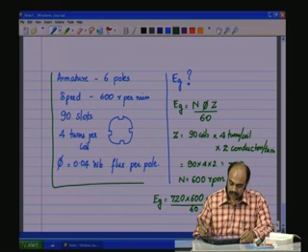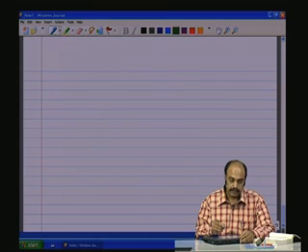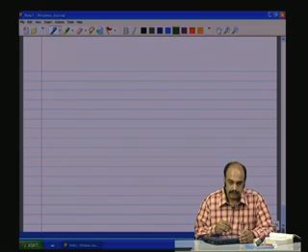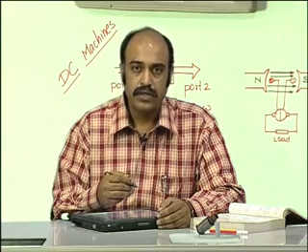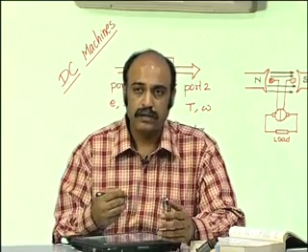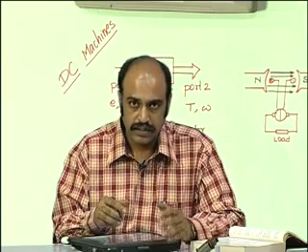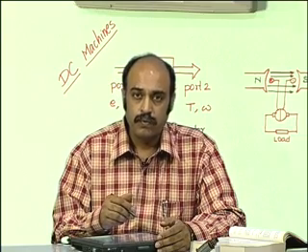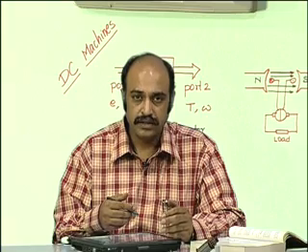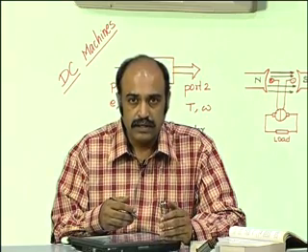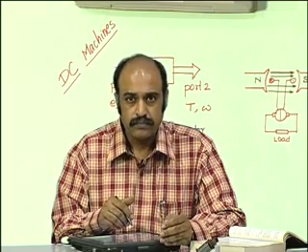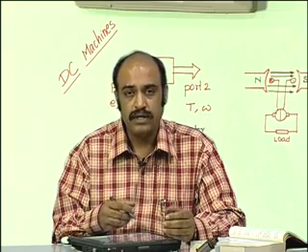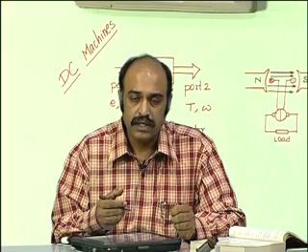Now, we know how to calculate the induced EMF across the generator. We need to look at the circuit of a generator and also the state equation that you would obtain for the generator. The general state equation, that is in the form x dot equals Ax plus Bu, y equals Cx plus Du, so that you can do any analysis on any type of generator, because all DC generators fall under similar constructional principles and operational principles, and thereby they can be mathematically modeled. We will look at the mathematical model of the DC generator. We shall also look at the voltage regulation characteristics of the DC generator, and the different types of excitation, that is how the pole flux is produced within the generator.